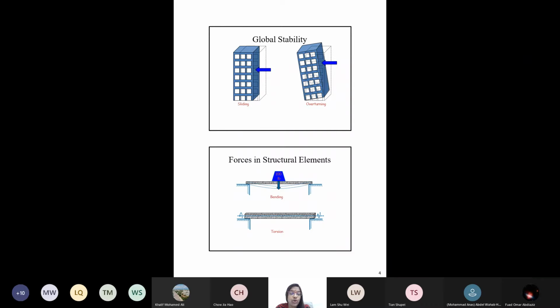Except the circular section, all other cross sections are subjected to warping, meaning the individual cross sections are deformed when the couple is acting, when the ends are twisted. The individual cross sections are not similar. On the other hand, in the circular one, the individual cross section is similar. The only thing is there is an inclination. The points are inclined while maintaining the cross section. Like if the diameter is 6, until the end it is 6 only.